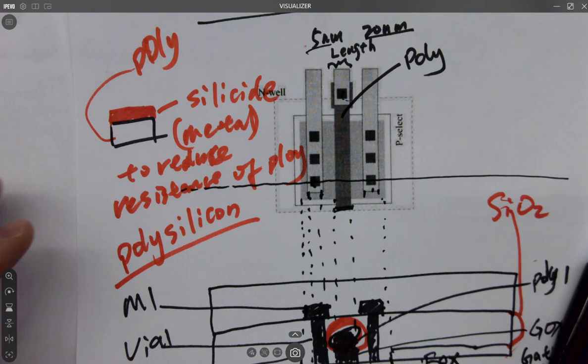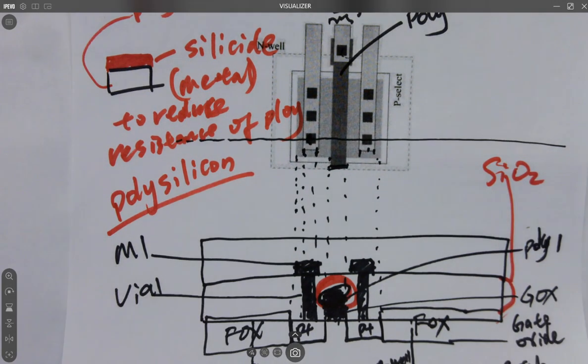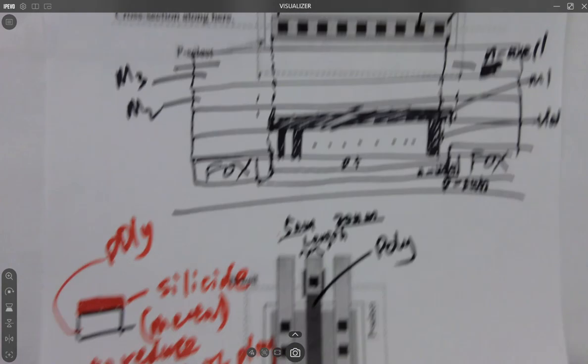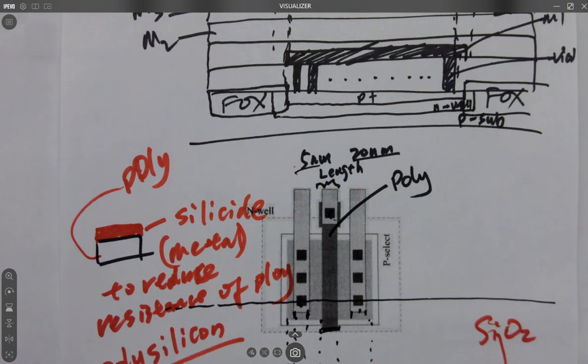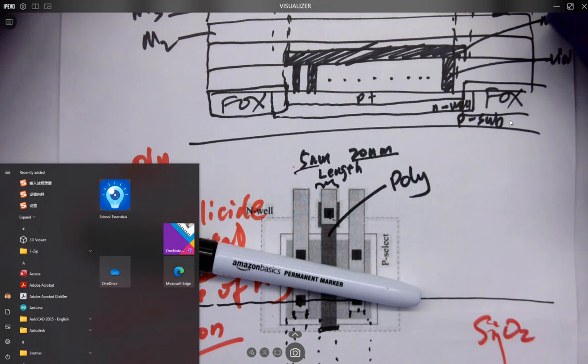Doable. So when you guys are doing the layout, you'll see this a lot. You know why? Because a lot of times you feel like it's so easy to directly extend the gate wire, right? I can directly use the poly layer as a wire, and I can connect to all the other circuits, because it takes time and requires some space to drill a hole to the top and connect to metal 1, then route it. So you want to be lazy, you just want to directly use poly, but eventually you'll find issues. Let me give you one example here.